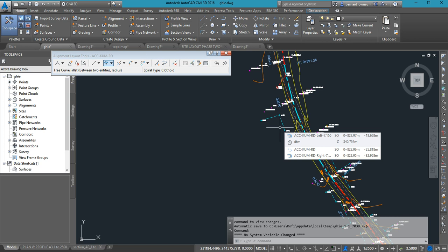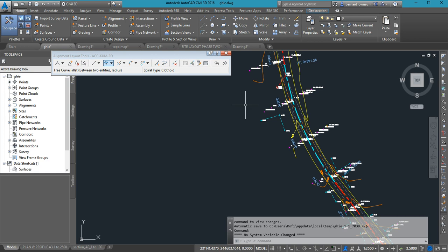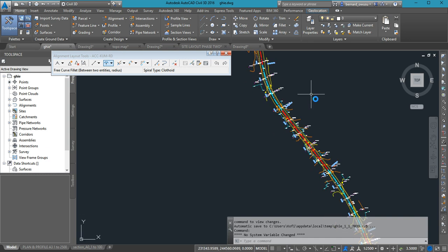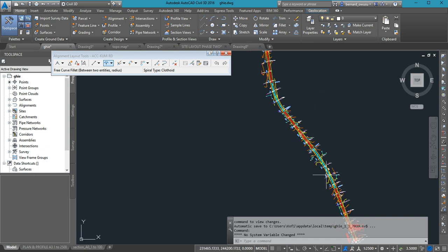So please, can we continue? With practice, you become perfect. Now, some of you had challenges. Why? Because if the tangent is too short, it will not be able to insert the curve, because by inserting the curve, it will take part of the tangent. Are you okay? So that's why, if you look at what I did now, I'm here, but some of you are still around somewhere here.